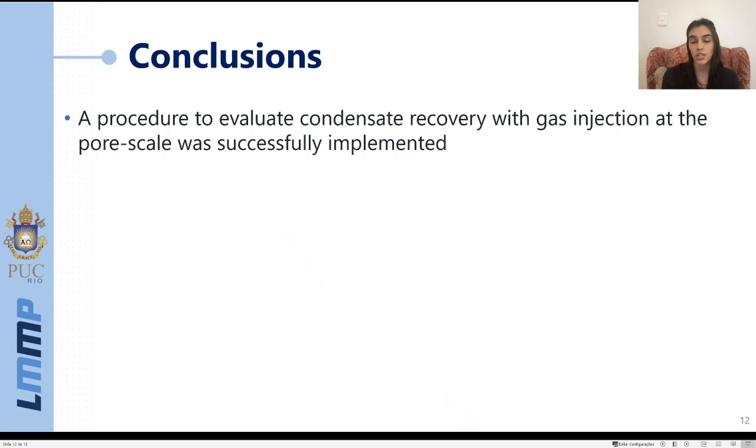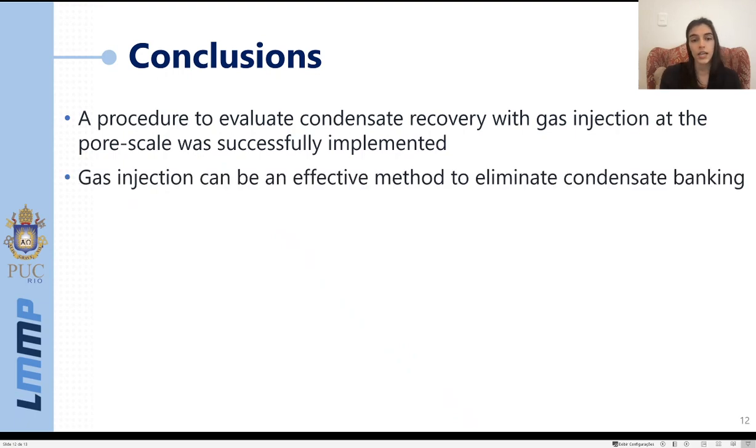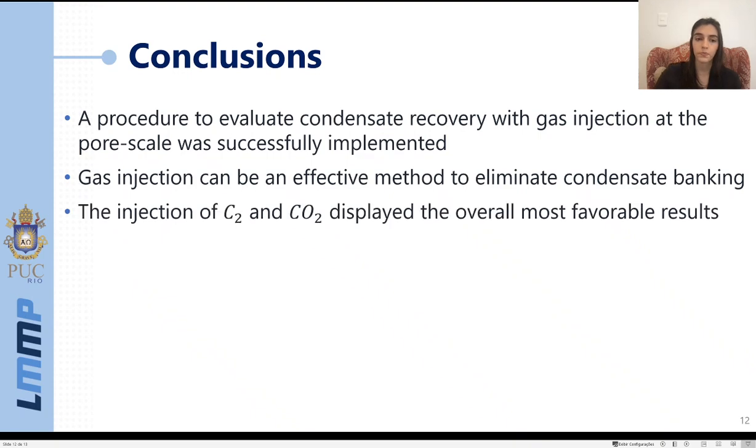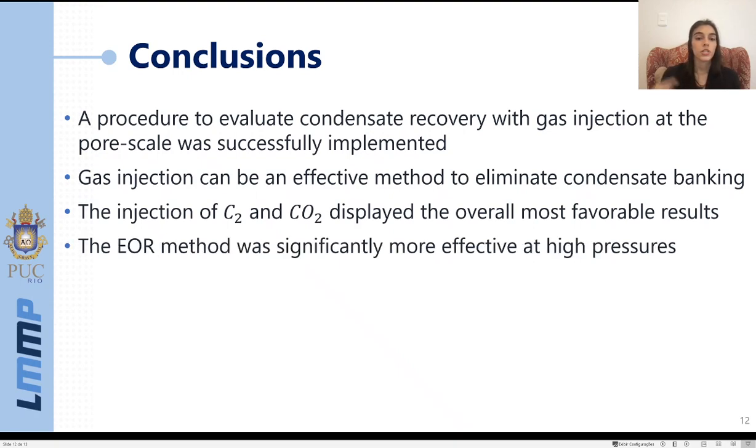So as the conclusions of this part of the study, we have that a procedure to evaluate condensate recovery with gas injection at the pore-scale was successfully implemented, that this method can be effective to eliminate condensate banking depending on the injection parameters, that the injection of ethane and carbon dioxide display the overall most favorable results, and that this EOR method was significantly more effective at high pressures.